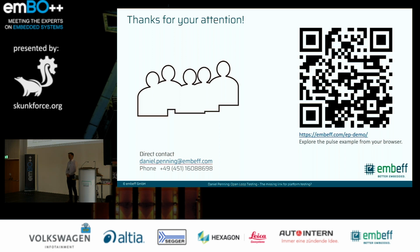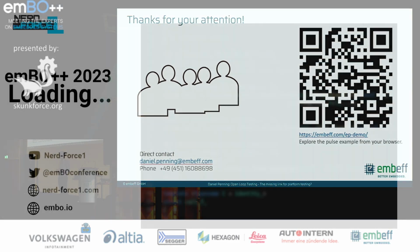You need to link your driver code with that software that you mentioned, right? Yeah, so thanks for that clarification. For open loop testing in general, you will not test the final firmware, because the final firmware obviously expects the whole environment. So you just take your drivers or the code you want to test and link this with a little library from us to some test binary. And this binary you flash. So yeah, thanks.